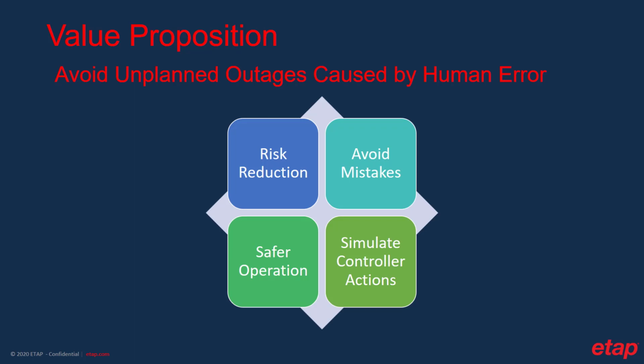Simulation of controller actions, such as load shedding, allows for training with the realistic response as well as validating load shedding logic to prevent costly interruptions. Too much load shedding can cause loss of critical processes. Not enough load shedding can cause total loss of production, unsafe operating conditions, and environmental concerns. Validation of the load shedding can prevent costly outages and equipment damage.